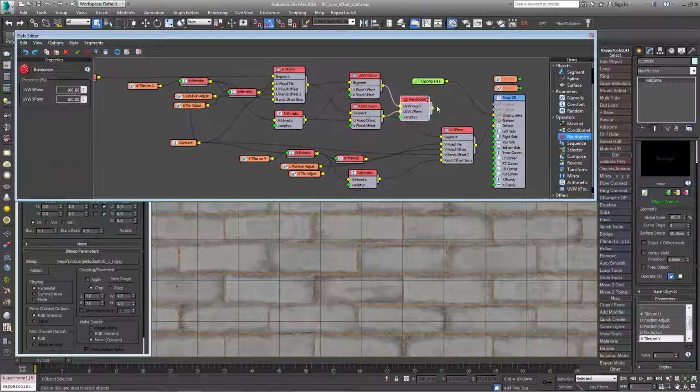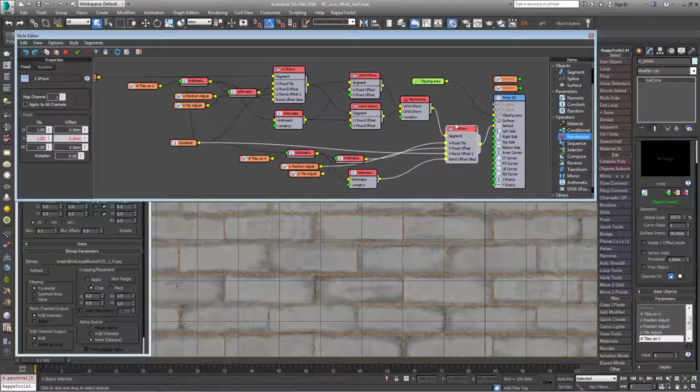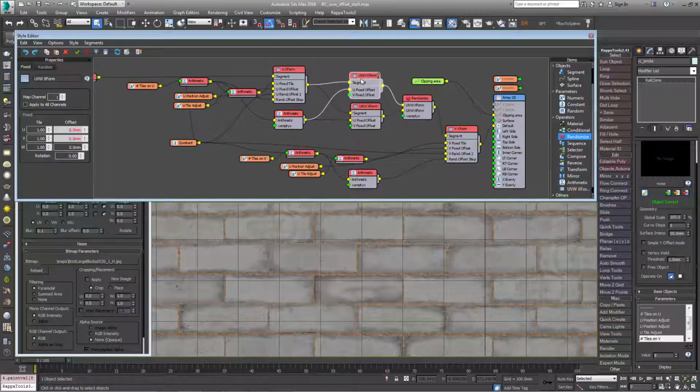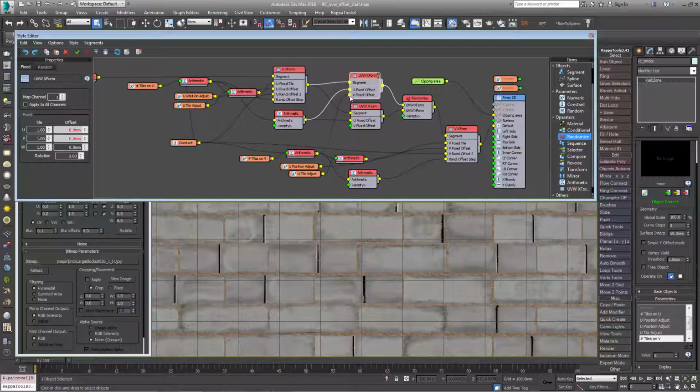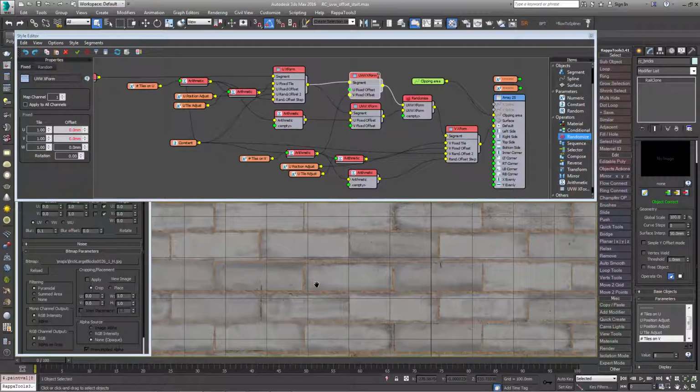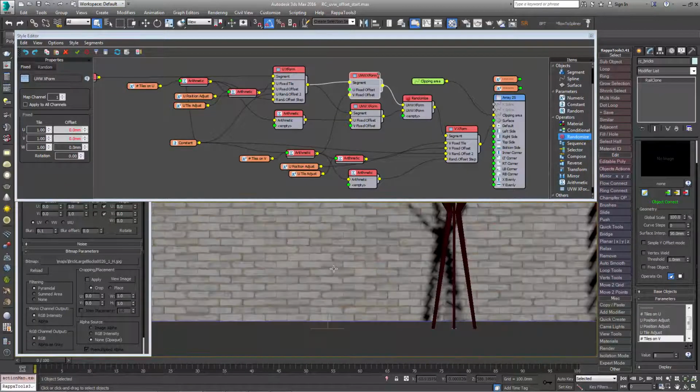So to offset one of these Xform operators to grab the even rows, attach the V divide node to the V fixed offset input. This reintroduces the joints to the center of the bricks, but this is because we also need to disconnect the U offset for this node. When the U offset is removed, the even segments are no longer offset on this axis and they sample the textures correctly. And that completes the setup.